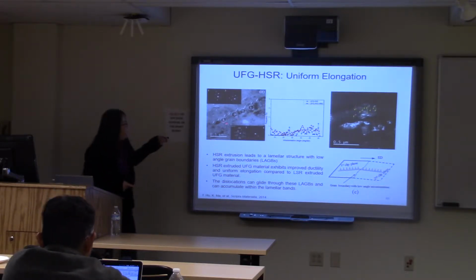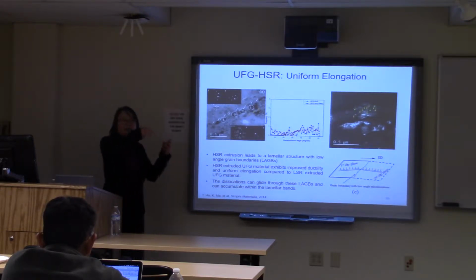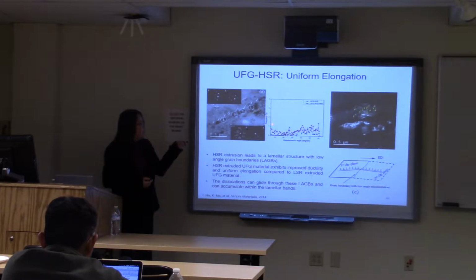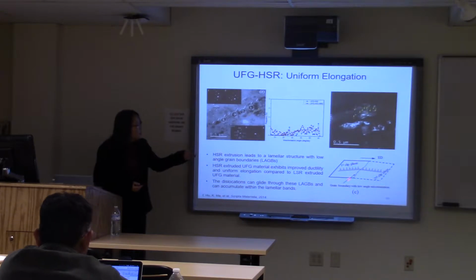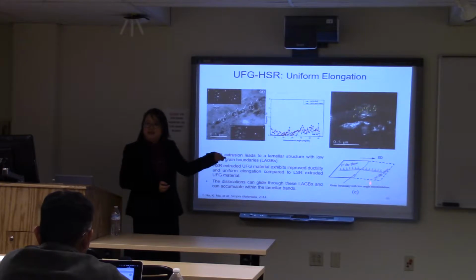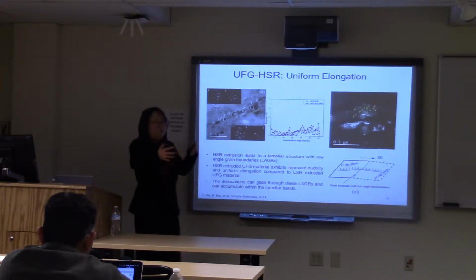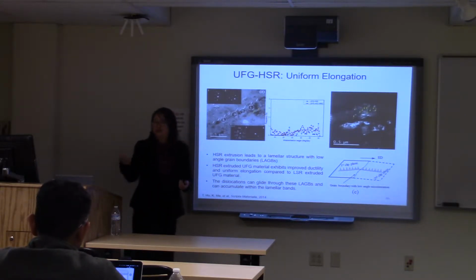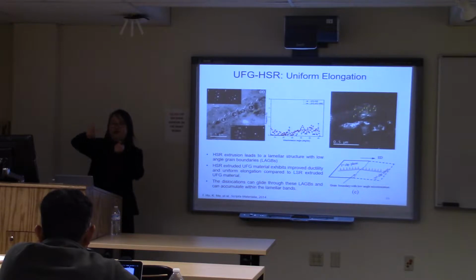It's because now we formed simple lamella structures. They are still formed by several grains strung up, but the grain boundaries between them are very low angle grain boundaries, so it's like smaller than 5 or 10 degrees here. And those low angle grain boundaries allow the dislocations to glide through those sub-grain boundaries, which allows you to accommodate more dislocations within that lamella structure, which gives you better ductility. Ductility is where you can deform the material without breaking it.